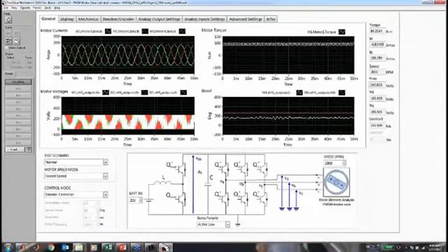What we're going to simulate today is a boost followed by a DC-AC three-phase inverter followed by a motor. So all the power conversion part is done in EHS. François just told us about EHS, so I'm going to demonstrate how it's managed inside the Simulink model. And everything is in HIL mode, so we have the real controller in the loop.